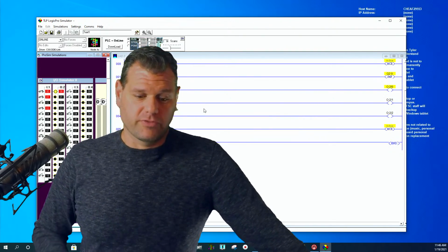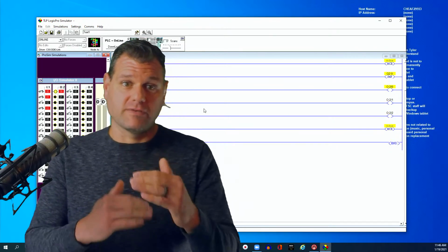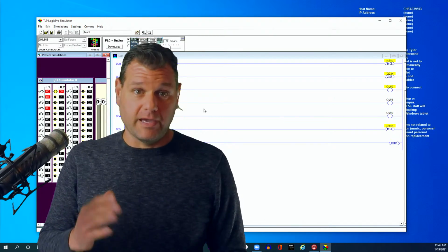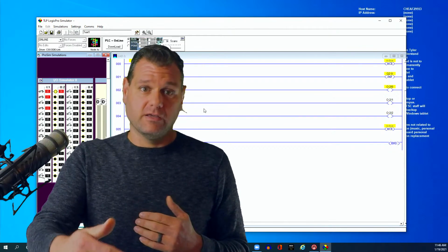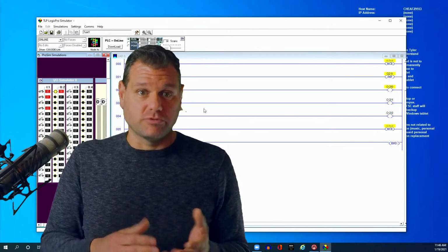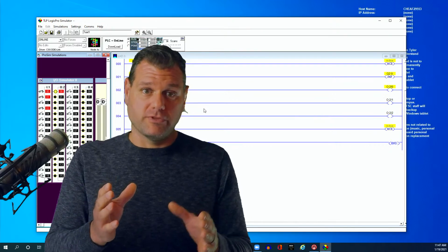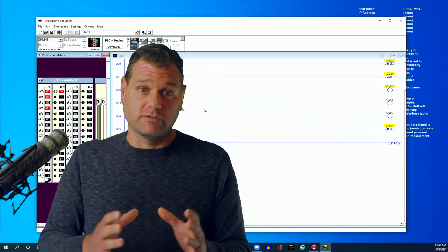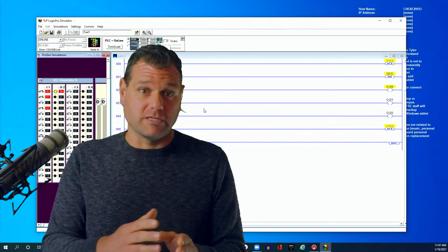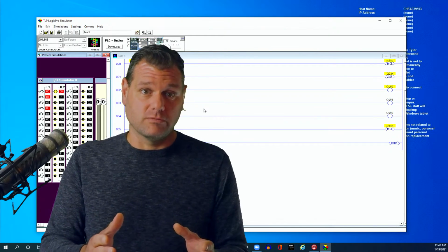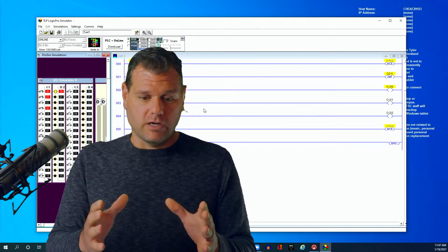That is correct. So the MCR fence only affects the stuff within it. And like I said earlier, the rule of thumb, you never jump to within a MCR fence. As a demonstration, I'm putting the jump within it, but it's really not advised because once it goes off, you lose the function of that jump if it's inside there.